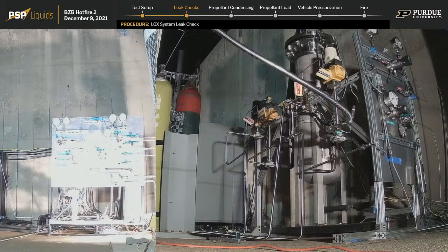So, out of the propellants on this vehicle, we have liquid oxygen supplied directly as a liquid, but for our liquid methane, we actually condense that from gaseous methane. Using a liquid nitrogen cooling loop, we run gaseous methane through a tank with this cooling loop on top of it, and by running it through this tank at a set pressure, we turn the methane into a liquid, and we use this liquid methane to fill the vehicle.